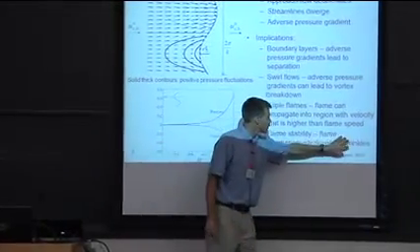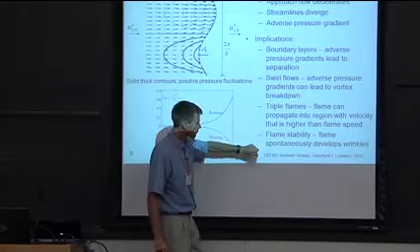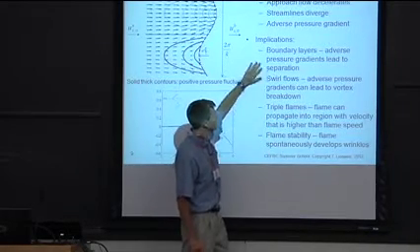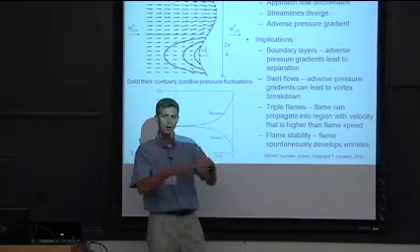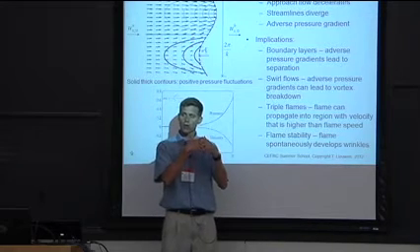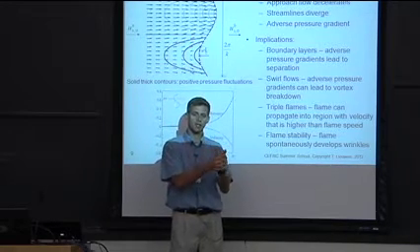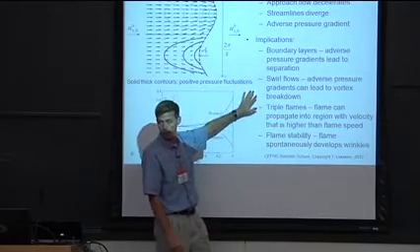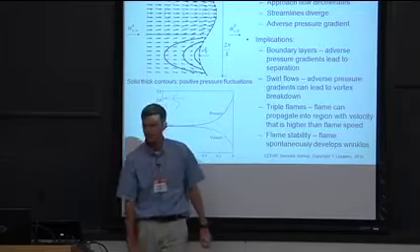So there's a lot of discussion in most textbooks on the Darrieus-Landau instability, but I want to emphasize that this same basic phenomenon, that a curved flame causes an adverse pressure gradient and flow deceleration, also leads to all these other interesting phenomena which control flashback and flame holding, which is what I want to emphasize now.